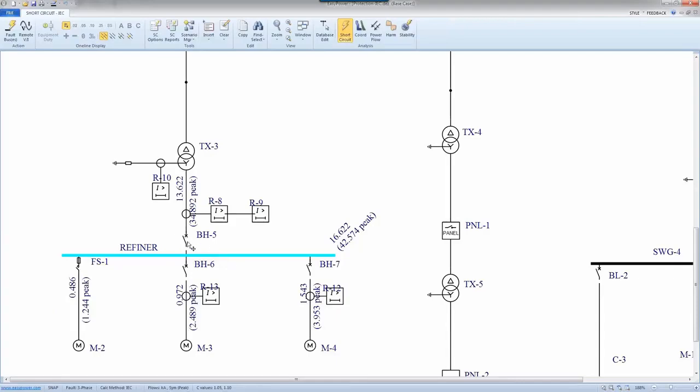So by replacing the frequency of, let's say, 60 with 24 hertz, R value remains the same, X value becomes smaller, and that's what method C does. It replaces the X value for the positive sequence of all these branches with a value which is 0.4 times the original value of X, keeps R the same, combines these values, finds the equivalent Z, and then divides that X by 0.4 again.